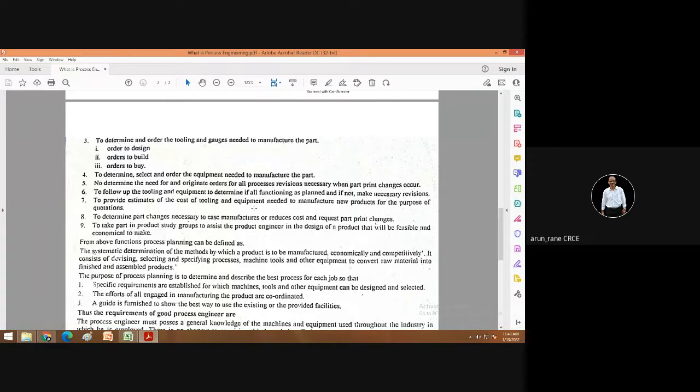Then the engineering change note is accompanied with the new blueprint and it goes to the shop floor. The old print is collected and stamped obsolete, obsolete meaning not in use. That is what is called the exit of the current drawing or withdrawal of the current drawing, and he issues the new drawing along with the engineering change note of what is changed. Of course, all the changes or revisions are already written on the new drawing. Besides, he also has to prepare the engineering change note.